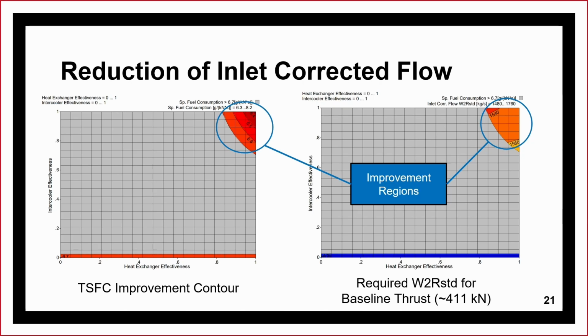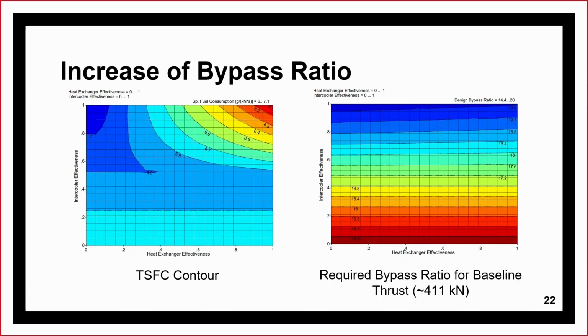I'd now like to pass it off to discuss changes in the bypass ratio in an attempt to improve the cycle performance. As Kevin mentioned, we also looked at increasing the bypass ratio to attempt to improve our thrust-specific fuel consumption while also maintaining our baseline thrust.